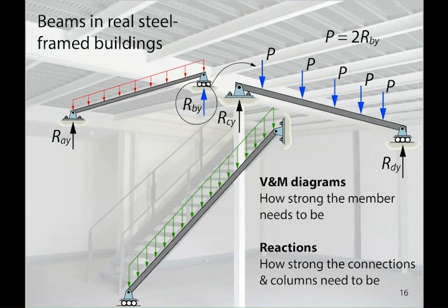All the loads from some of the joists and some of the girders are going to be supported by the columns. And so when we calculate the reactions in those members, that's going to be the action or the axial force on the columns. And so we need to understand how the pieces work, but we also need to understand how all those pieces fit together if we're going to figure out how the loads get from the floor down to the foundation. And that's a key part of structural engineering, not just understanding how the components work, but how they work together to form a structural system.